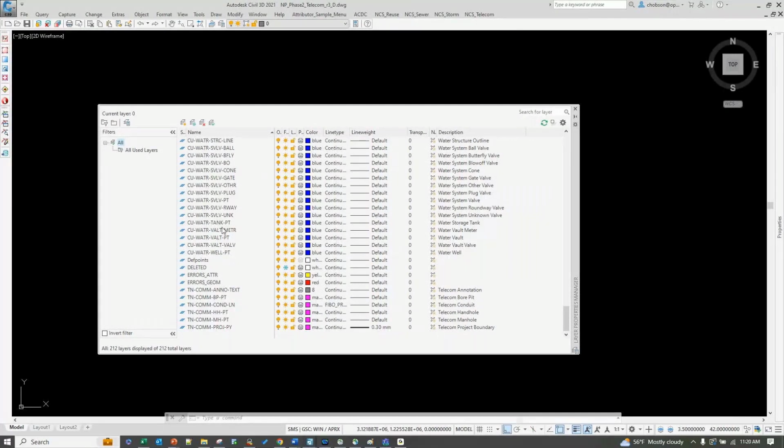The problem here is, by the way, if you tell a CAD person, hey, here's a whole new set of layers, and yes, they are National CAD standard compliant with the guidelines. So it's got the discipline, then the major, minor, minor, and you'll see a little bit of GIS stuff in there where lines have got LN for line and points are points and text is text and polygons are polygons. So we kind of split this up.